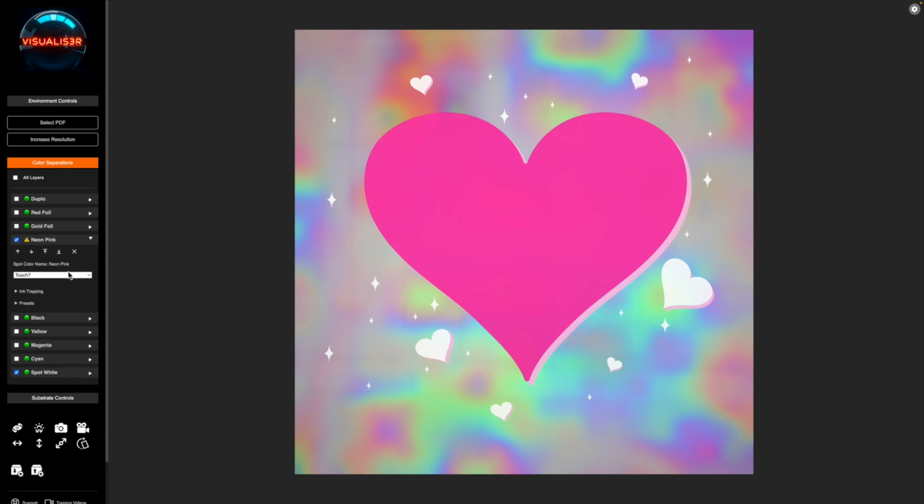So that is the typical pink that's built into the Touch 7 system, but that's not the same color as Fujifilm Revoria. Fujifilm Revoria's pink looks like that. It's a much cleaner, kind of like Barbie bubblegum pink. And what that means is when you start layering up color behind the back of it, you don't actually get a red. Now you would never know that if you're actually designing and what you see on the screen shows you red, but in reality when you print it, it looks more like an orangish red. So very, very important of how different company pinks react with combinations of CMYK.